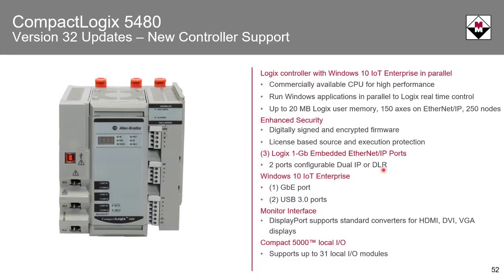And then just for your reference, Windows 10 IoT is a specialized edition of Windows 10 Enterprise that promises the longest intervals between feature upgrades of any Windows operating system. It's supported with security and stability updates for 10 years. Now, it doesn't have things like Windows Store, Cortana, Edge Browser, OneNote, Calendar, those types of features. But it will run a FactoryTalk View SE local station or an ME station.